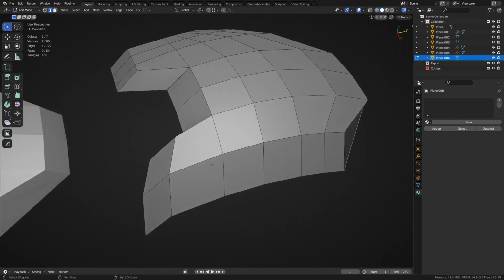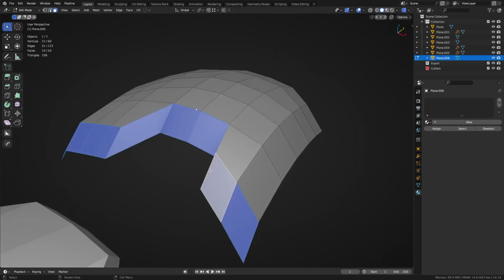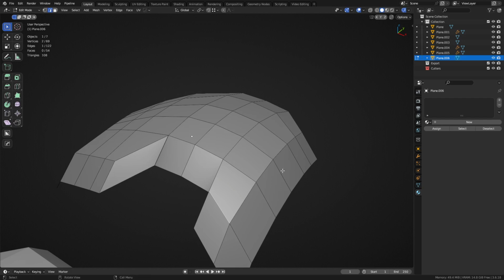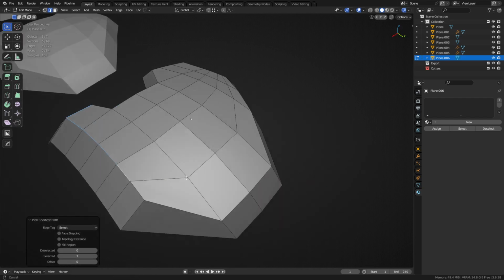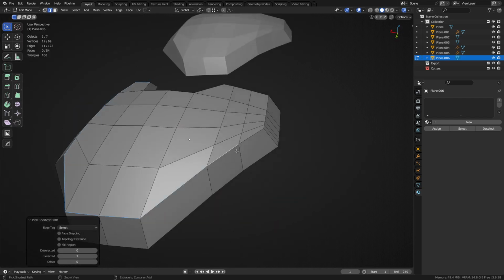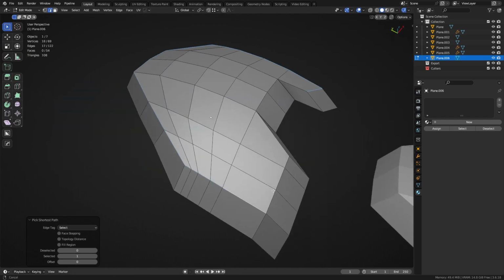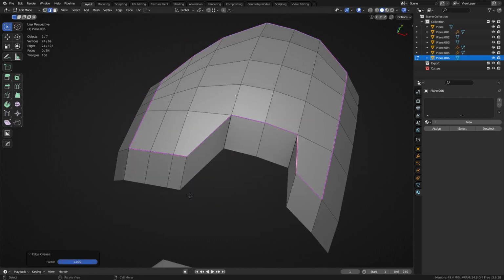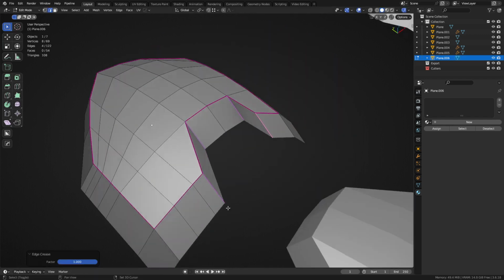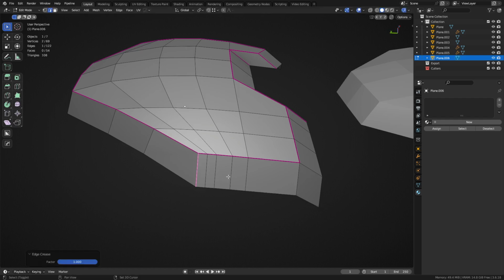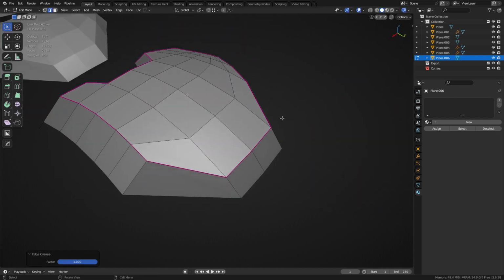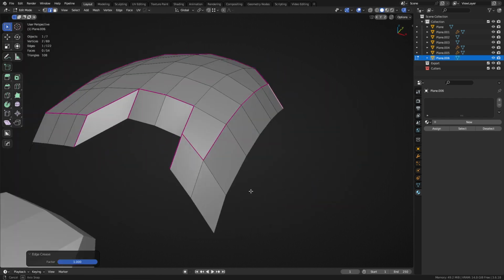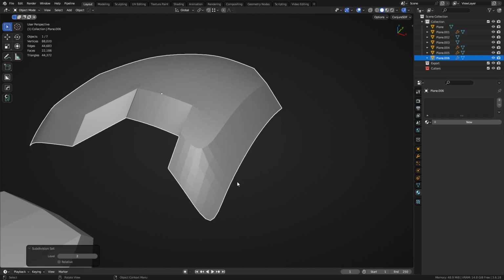We don't do bevels either. We do creases. Okay. So let's crease certain edges. We'll do this top one all the way around. We'll hold this sharp, and this sharp by creasing it. So Shift E, by the way. That's all we're doing. We'll crease that one. We'll leave that rounded and we'll crease this one and this one. Come back over here. Let's Control 2 to subdivide it.